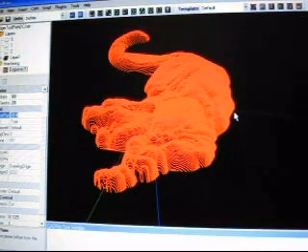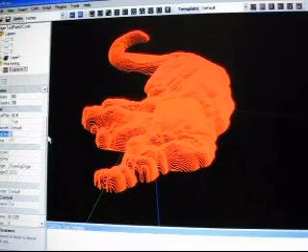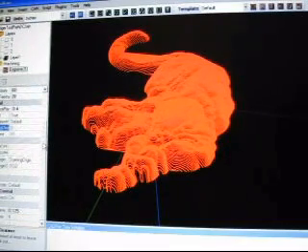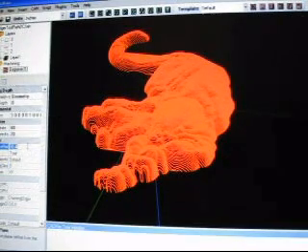We'll just find and replace those rapid motions in NC Corrector, and we'll be able to do that very quickly. So basically, that's all you need to do. This roughing clearance does nothing. That's the only parameter we're really interested in, this clearance plane.